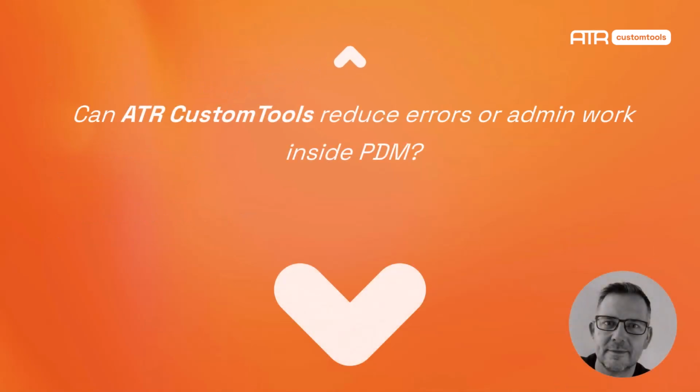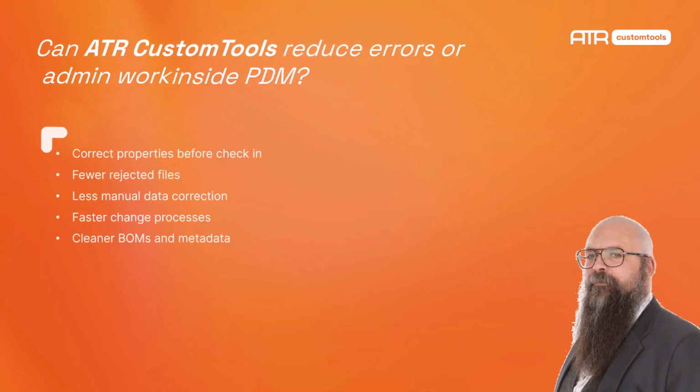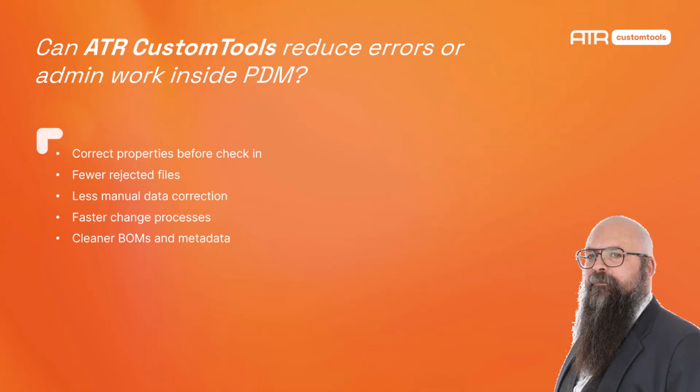Have you seen concrete examples where Custom Tools reduced errors or admin work inside of PDM? Yeah, correct properties before check-in is a big one. Fewer rejected files, less manual correction by admins, change processes become faster. Bill of materials and metadata are cleaner, and overall, the administrative load inside PDM goes down.